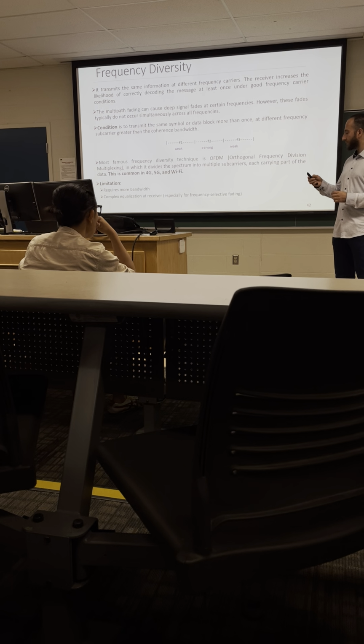The limitation here is increased because we are speaking about time. First of all, it increases the transmission delay. Imagine that you need to send one symbol and you repeat it 3 times. I send, I wait, I send the same symbol, I wait, I send the same symbol, I wait. However, in space diversity, you send the whole sequence of repeated versions at the same time, simultaneously.